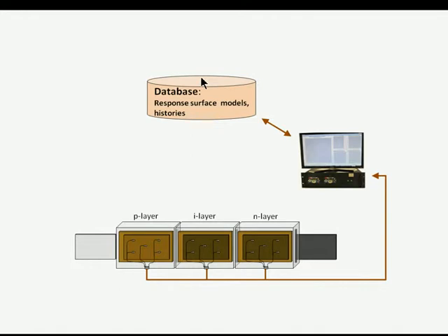As each panel is undergoing deposition, our software retrieves from the database all similar histories and predicts what the final quality of the panel will be ahead of time. Once the suitable response surface model is identified, it is used to create an adaptive correction, which will adjust the process in advance in order for the panel to achieve the same best quality as the chosen model.